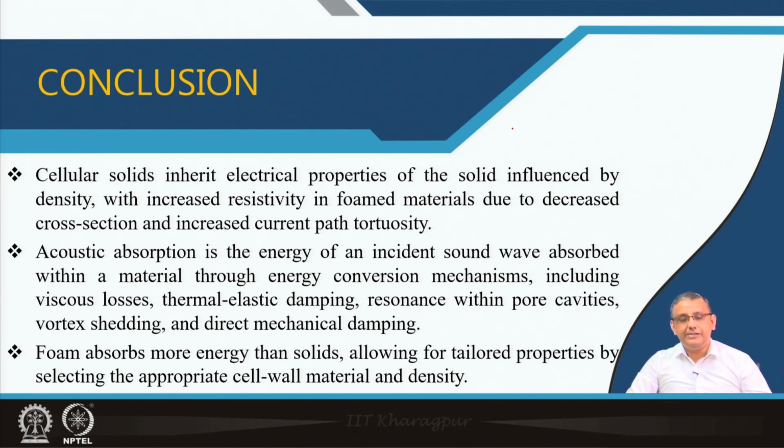Second, we learnt about the acoustic properties. We learned that for sound absorption, the foam should be open cell in nature, and it should have very tortuous pore shapes, because the tortuous pore shapes will interact with the incident sound energy, and by continuous reflection and absorption, the sound energy will be absorbed, and this way noise pollution can be mitigated.